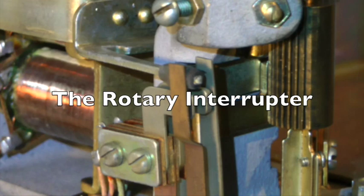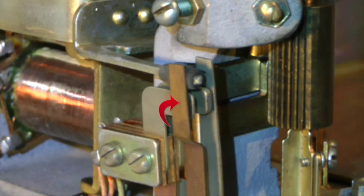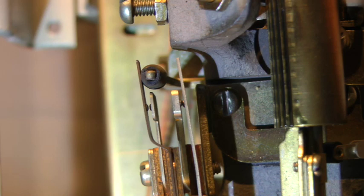Also associated with the rotary magnet is a set of contact springs called the Rotary Interrupter springs. This spring set is operated by a rotary interrupter lever which is attached to the rotary armature. Each time the armature is attracted to the rotary magnet, the attached lever pivots and operates the rotary interrupter springs.